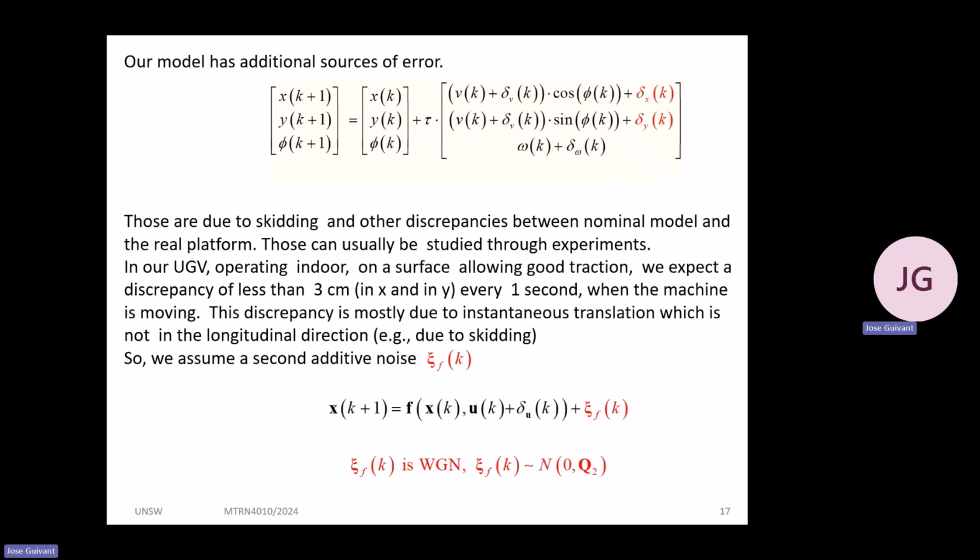It doesn't happen in our particular case because the machine was moving slowly and the terrain was good, perfectly two-dimensional, everything was beautiful. So there was no skidding, there was nothing failing in the traction of our machine. But in a real application, when you are dealing with more complicated terrain, or the machine is moving suffering high, intense acceleration, and it's skidding, then you will need to consider that. You will need to get a statistic about how large those uncertainties are. In our case, it doesn't happen. But in general, keep this in mind.